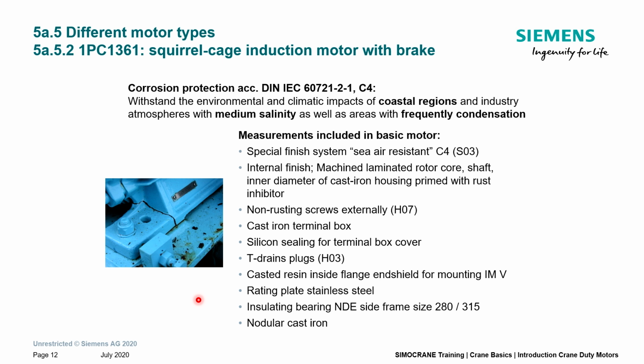On this slide, you can see that there are lots of features which are relevant for rough, harsh environments in outdoor areas. It covers all issues so that the motor will resist for a very long lifetime. In this picture you see a broken leg of this motor. This can happen through wrong mounting, but can also happen due to vibration. For example, when the service crew climbs up the motor, or a forklift is banging against this motor, because there is lots of activity around these gantry motors.